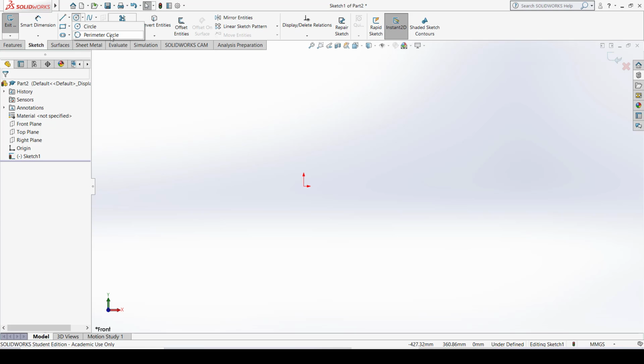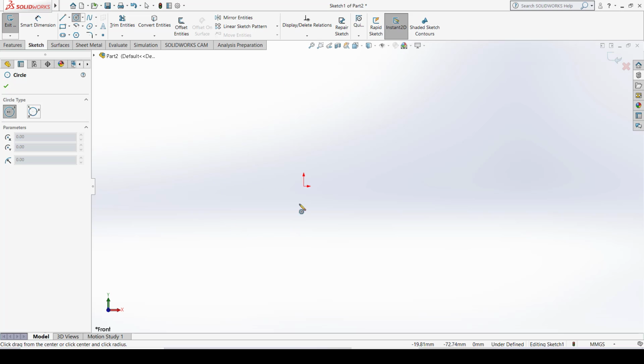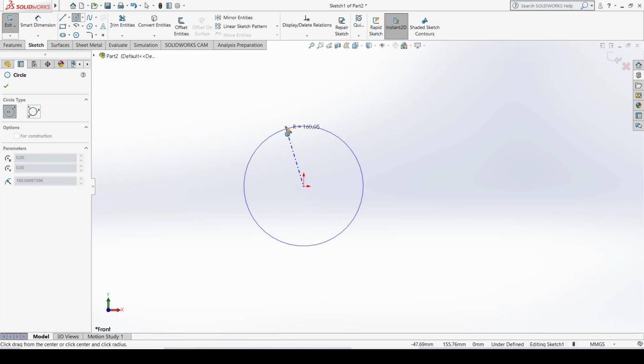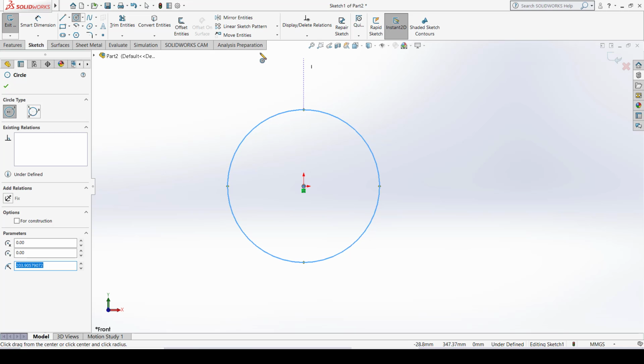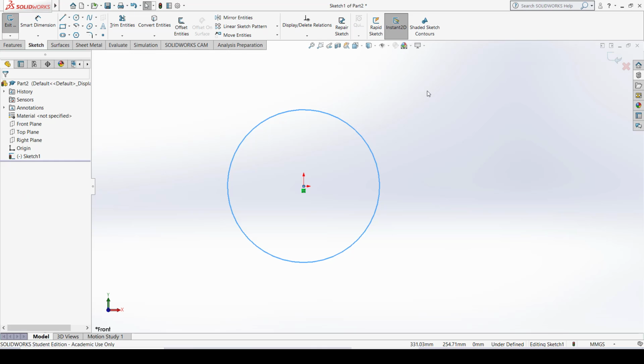Okay, so let us say I just draw a circle, the first circle here. So I go to circle, normal circle selection, and then I go to the origin. Say we started with the origin, so I click here, and now you give the second point, that is your radius point of the circle. So this is your circle drawn here. Okay, and now press escape to end the command. This is how you can draw the circle.